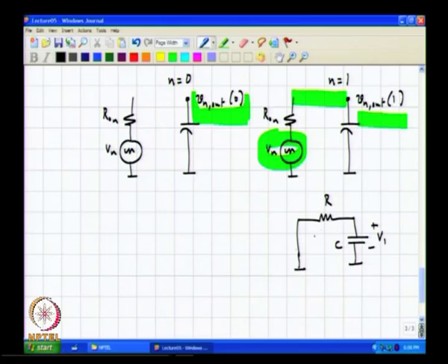Now, if the RC time constant is very small compared to the clock period, what do you think will happen to V1? It quickly discharges, which means that at the end of the next cycle V1 is completely discharged, and the new voltage held on the sampling capacitor C1 is largely a function of only the input waveform during that next cycle, which is completely uncorrelated because it is white noise.